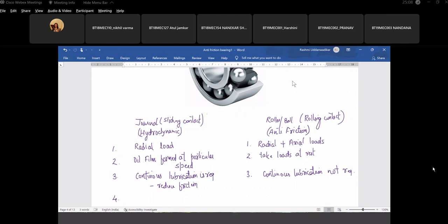Okay, about temperature sensitivity. Okay, what else? Shear force. So the hydrodynamic lubrication works on the concept of shear force between the layers of oil, and here there is a concept of contact stress between the rollers, which is the governing parameter.